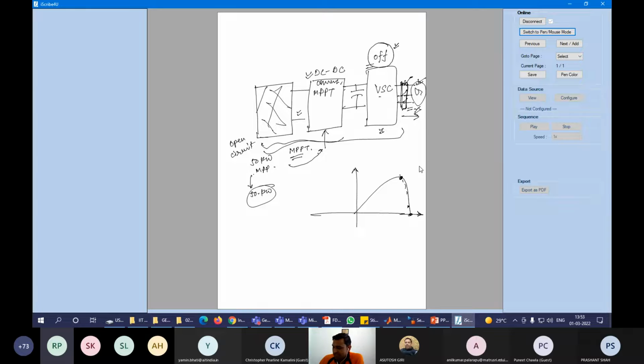So what will happen in that case when it is operating at MPPT? You might have seen we have a reference DC link voltage, some value of actual sensed DC link voltage, and a reference DC bus voltage. At that moment, your control will fail when we have excess power at the DC bus, and this voltage may rise from 700, if you are talking about a three phase 700, to 1200, 1500, or even more than this value.